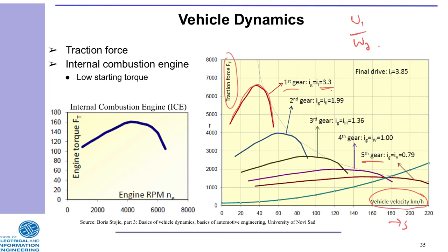Okay. Remember the principle was as you have the box, you have your gearbox, T1, omega 1, T2, omega 2. As the speed increases, the torque will drop. Okay, and that's what we are noticing here, that now omega 1 at higher gears is less than omega 2. Okay, so which means the torque at the output, T2, is now less because omega 2 is bigger. And this is the relationship we are seeing in this curve.